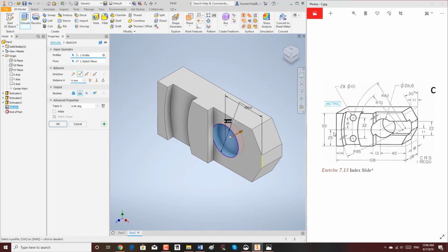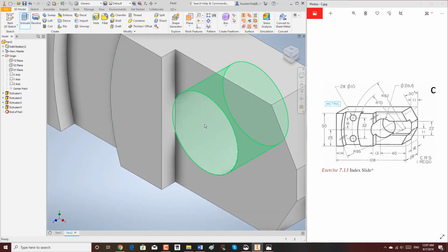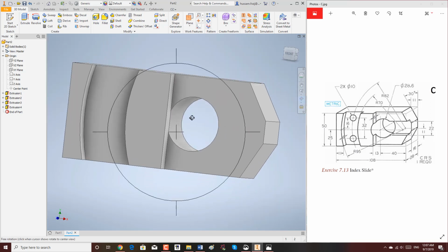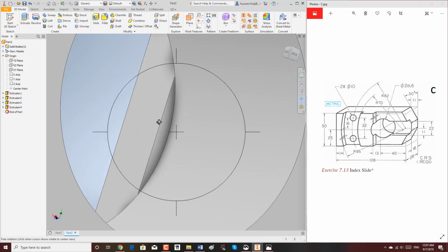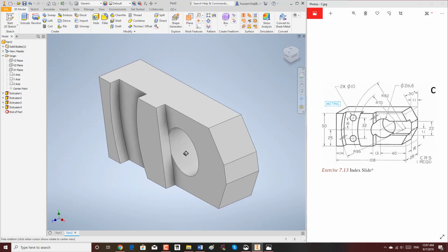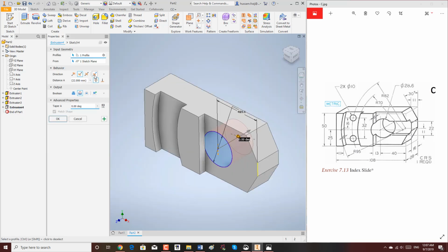See, if I did extrude cut only one way, down to the bottom like this, I said all the way through down, I will end up having this cut. But from this area I still have distance, which I don't want to keep, because here it's not available. It has 6, as you can see. Okay, so I will right click, edit feature. I would choose another distance.